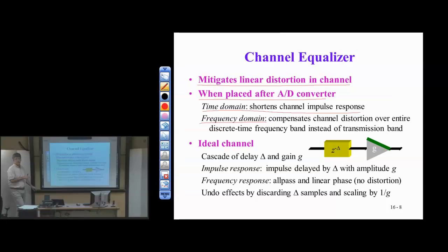And we also have additive noise in all of this to worry about. So our equalizer often needs to worry about amplifying the additive noise that's there, which is another side to worry about in all of this. For this particular discussion, we're not going to worry about the additive noise. We're just going to go after the filtering effect in the channel that can be modeled as linear time invariant, or even linear time varying, and we'll get the linear time varying part by adapting the equalizer with time. So I track, if you will, the changes in the frequency response over time.